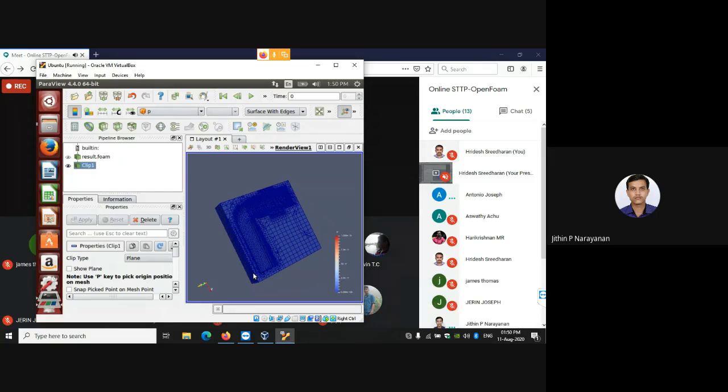So when I created the mesh files, inside the constant folder, I was trying to create the block mesh. Inside the constant folder, there was a folder called polyMesh. So in order to see the mesh, what should be the command? That is what I'm asking.